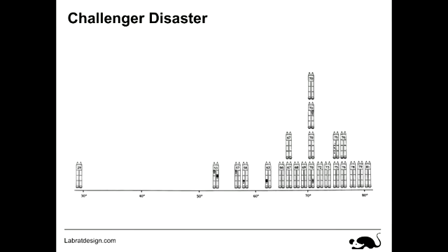And what you can see, again, by organizing it like this, is that you start to see damage done to the O-rings at temperatures at around 65 degrees and below. Almost every single rocket has damage done to it at those temperatures. This was going to be the launch temperature, all the way down here, all the way down below 30 degrees. Even at 65 and below, every single O-ring that they had tested at 65 degrees and below had damage done to it.